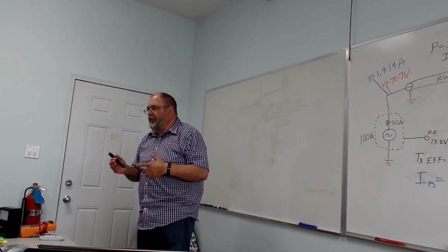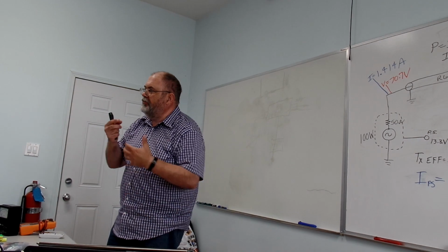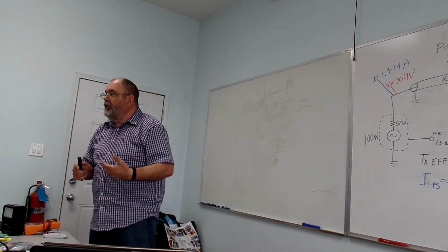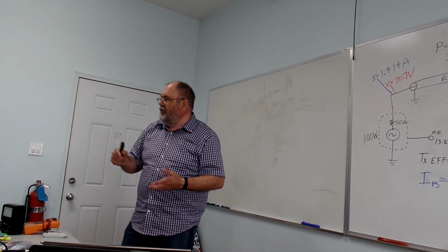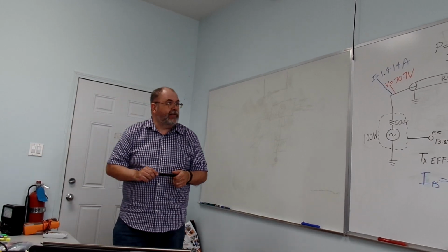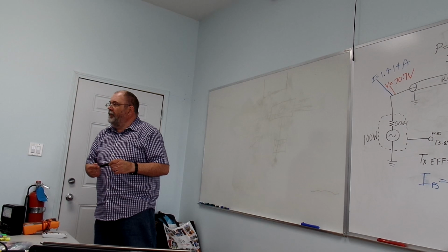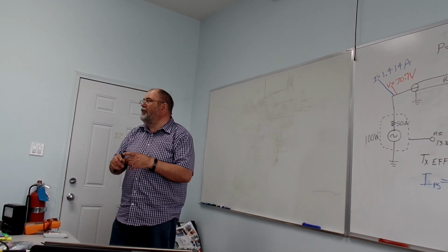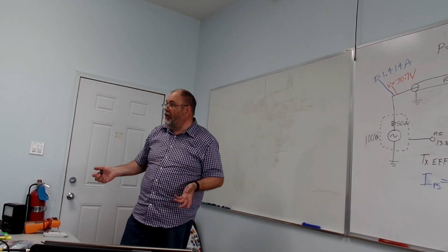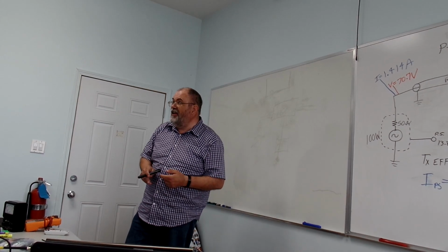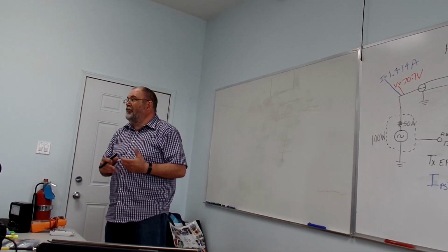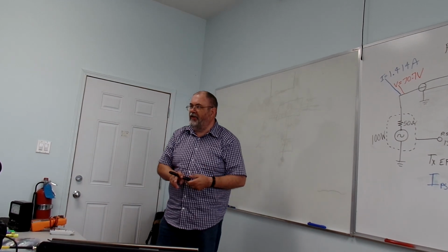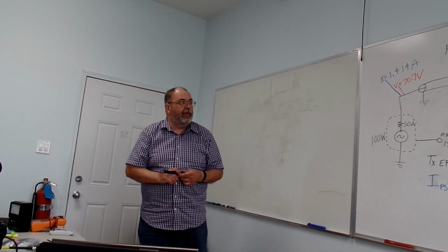Even guys, if you've transmitted with your handheld radios on high power for any length of time, you can actually feel the body of the radio starting to heat up. That's because these rubber duck antennas are basically not even an antenna, they're a piece of rubber. So the majority of your power is being reflected back into the radio. Even at low power, 3 watts or 5 watts, it doesn't take long because your radio now has to dissipate the power that it's putting out plus the power reflecting back, which is a lot in the case of a handheld. The antennas are very poor.